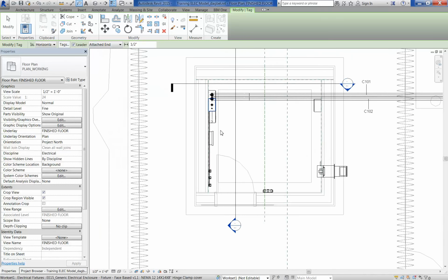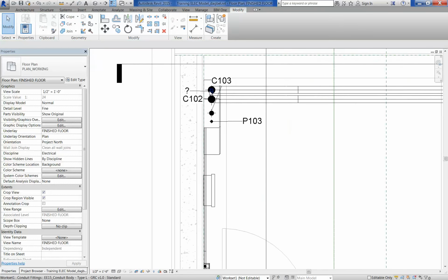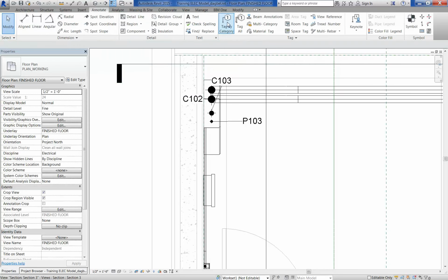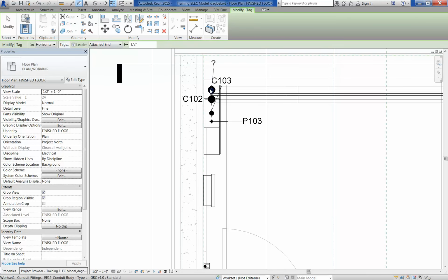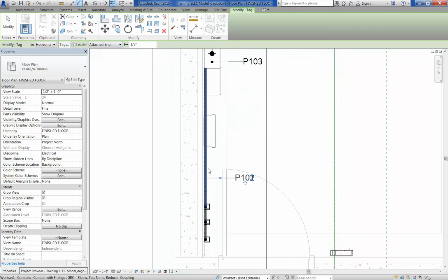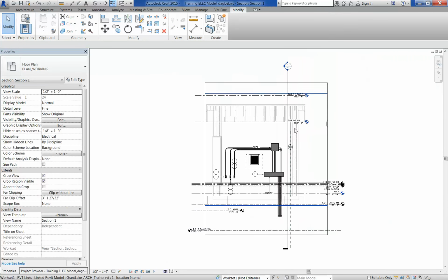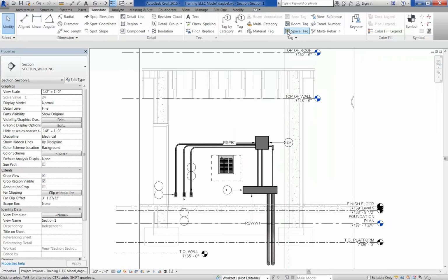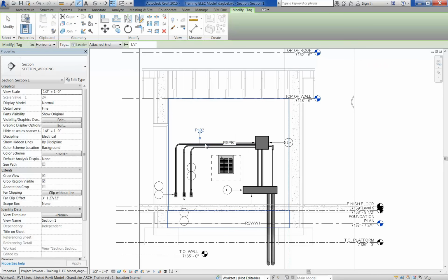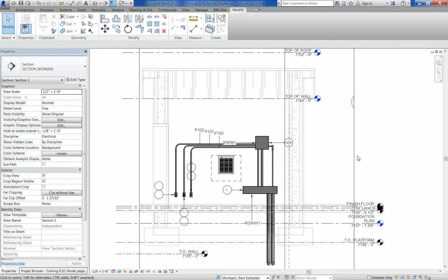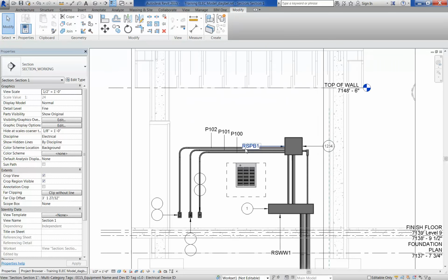And so you can see here that it's placing a tag for each numbered conduit. That section didn't have a number. There we go. For each numbered conduit shows the tag. You can do that in any view, and then if you have to go about and change the conduit number, the tags will automatically update as necessary. But this makes annotating really quick and painless.